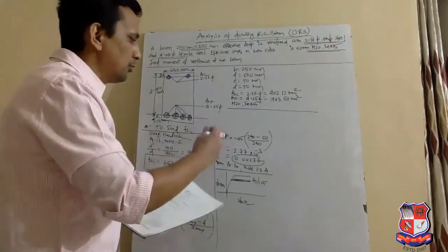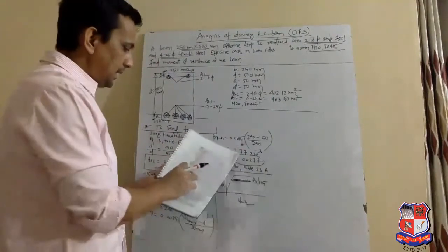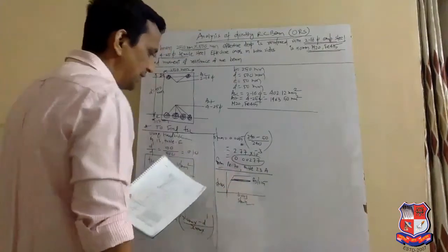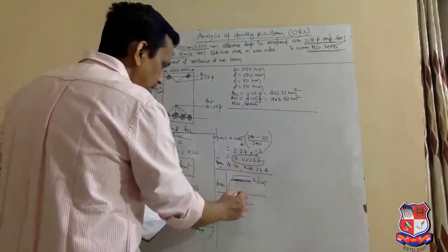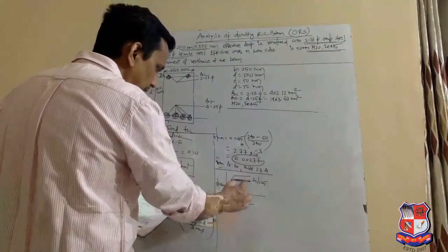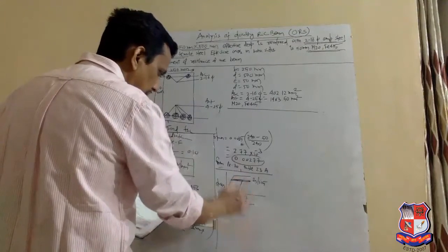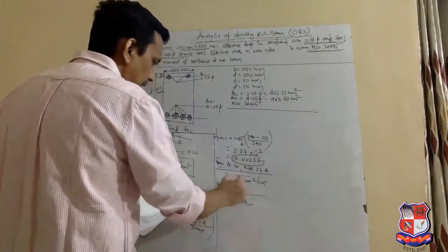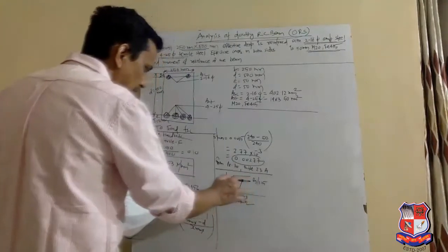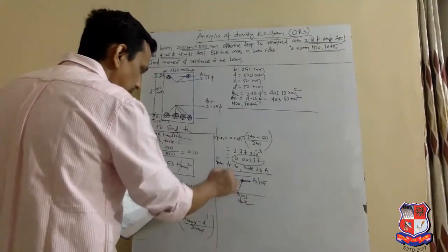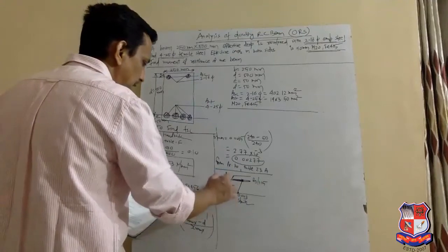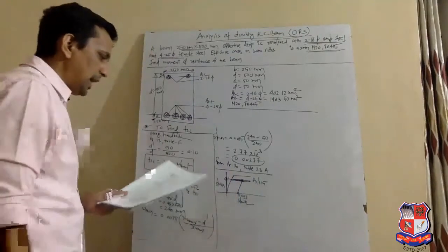It means almost 0.028. And in IS, they have given the value for 0.003, so it is almost near to 0.003. Again, what we have to do next, we have to draw the parallel line from this line. And this parallel line, when it intersects, we have to extend that line, and that extended line where it intersects on the vertical line, this will give the value of FSC.